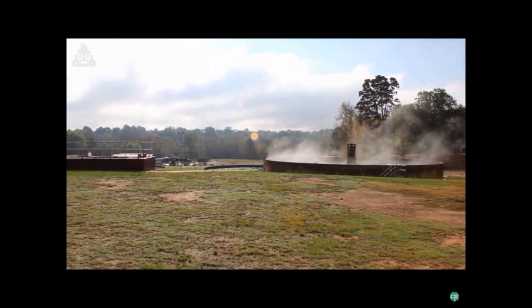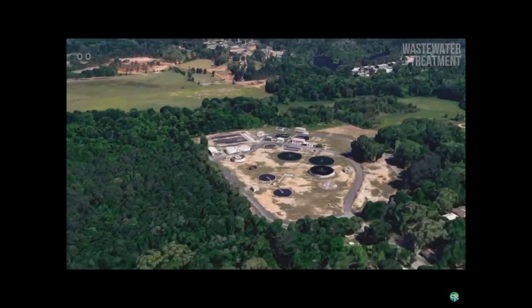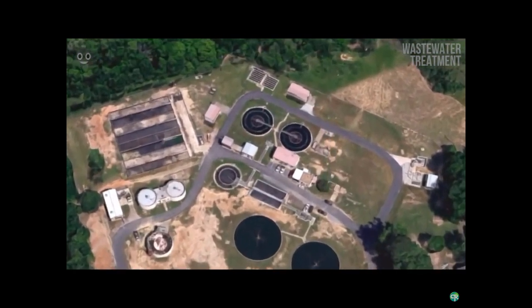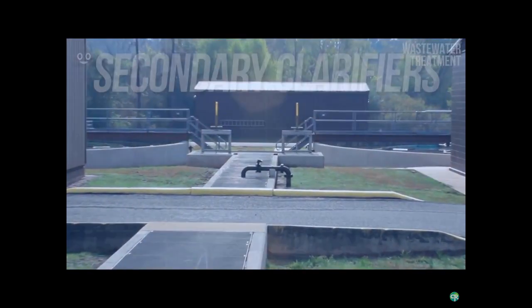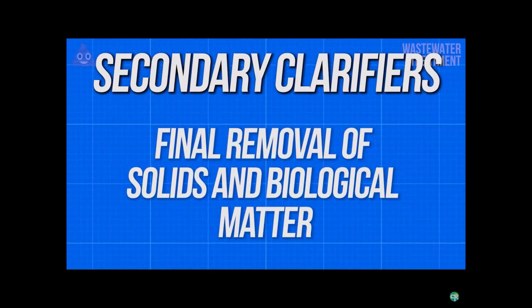Following the aeration basins, the effluent along with much of the sludge is pumped into a secondary filter or clarifier, where some of the sludge is removed and pumped back into the aeration basins as the return activated sludge. Further settling of larger particles is also accomplished in these basins, as it is the final step of the process that will remove solids and larger biological matter.